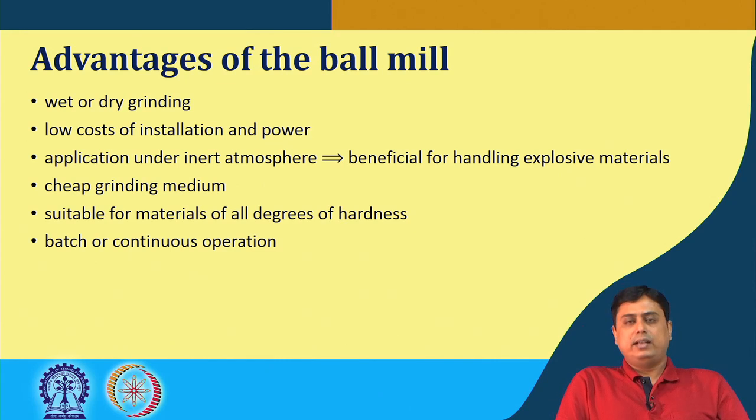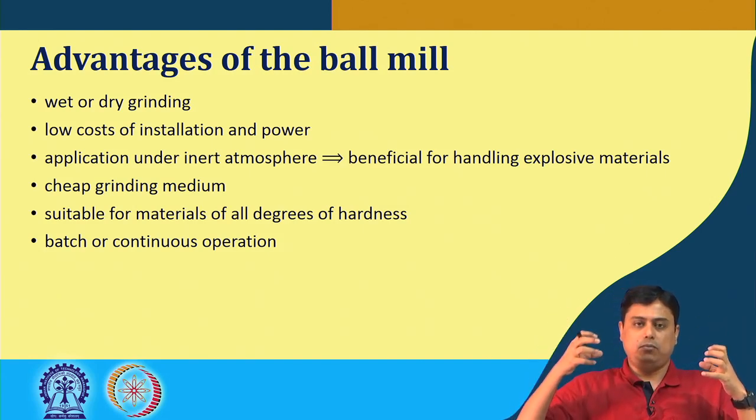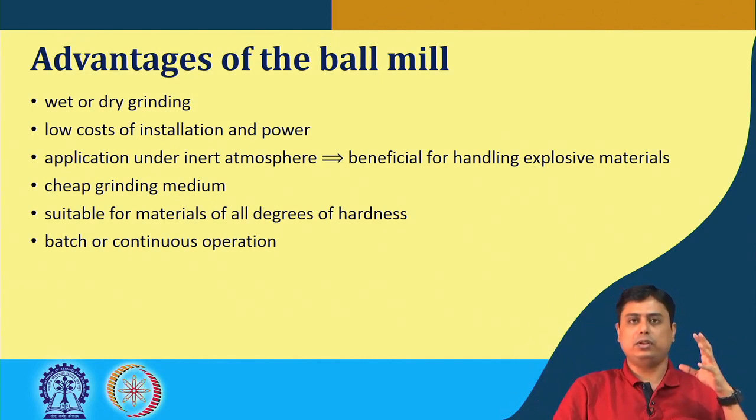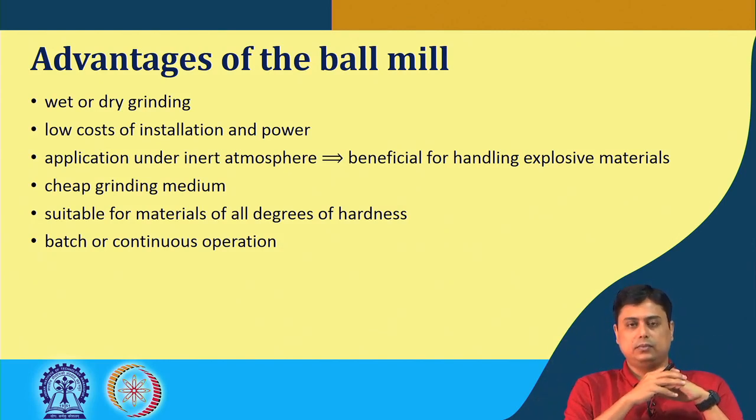So, there are several advantages of a ball mill, because we have seen it can be operated in wet or dry grinding scenario. It has a very low cost of installation and power consumption, because it revolves at a very low speed. It can be applied under inert atmosphere, because the inside chamber is basically enclosed. This whole chamber can be operated under inert atmosphere, which is beneficial for handling or crushing explosive materials in absence of air.